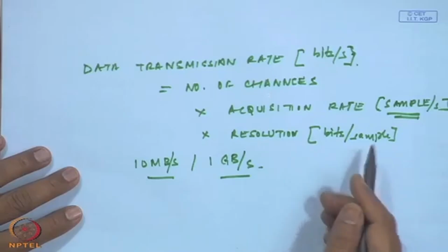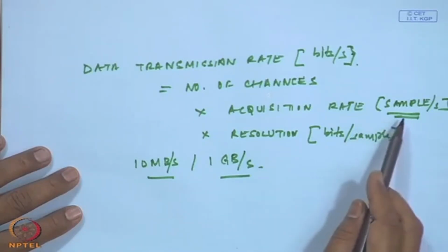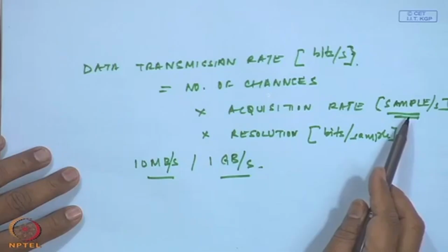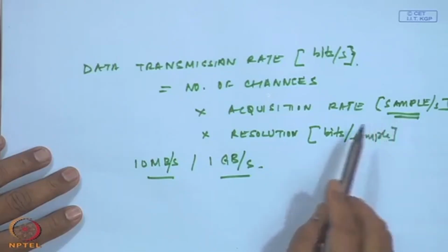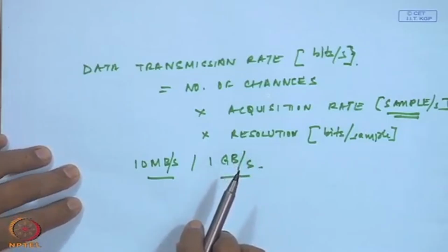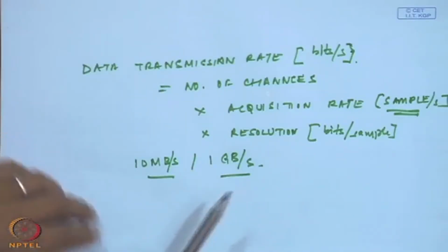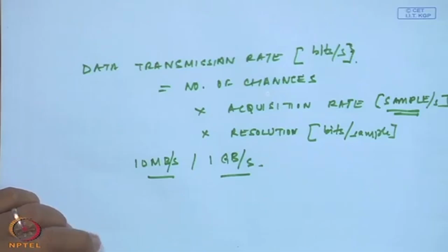Typically, the resolution people use nowadays is about 16 bits or 24 bits per sample, and for a low frequency signal, it is easier to transfer by wireless. But when we are talking about high frequency signals, where you want to send 10 channels of vibration data over wireless, the data transmission rate of present wireless technology limits these levels of data transfer.